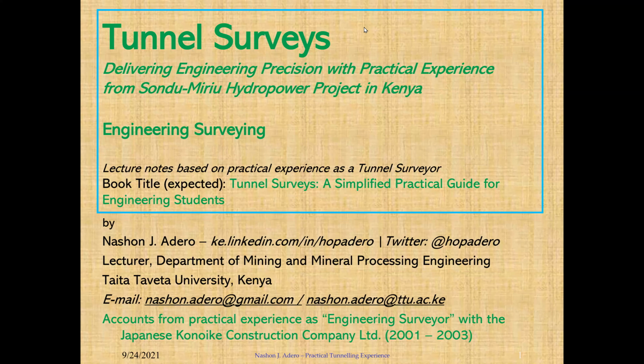Dams could be deforming on a mining site, for example, and you need periodic measurements to detect if any built structure is going out of the designed geometry, maybe settling over time, subsidence. So we have subsidence engineering, which is critical to mining operations to ensure safety in mining areas, to monitor those dams. So deformation monitoring is also a key assignment under engineering surveying.